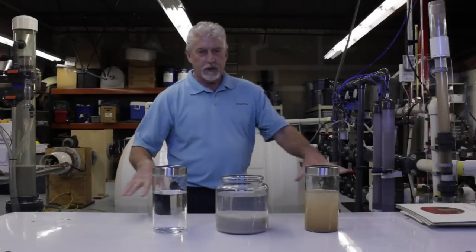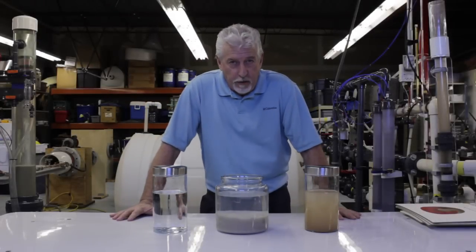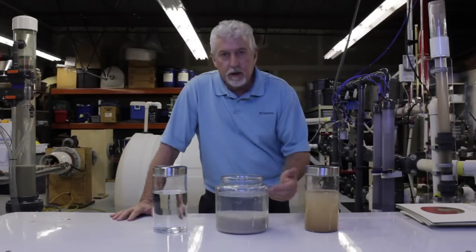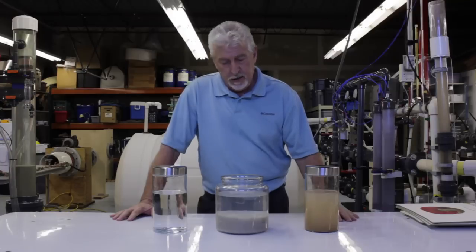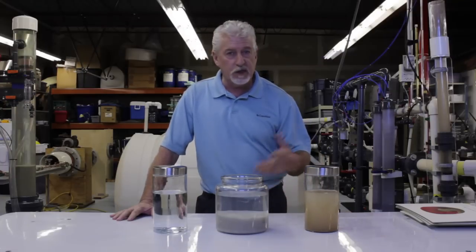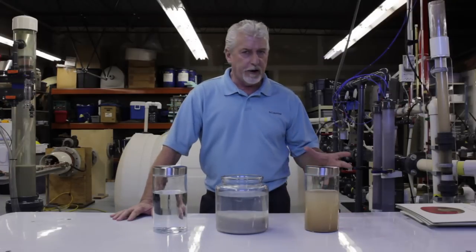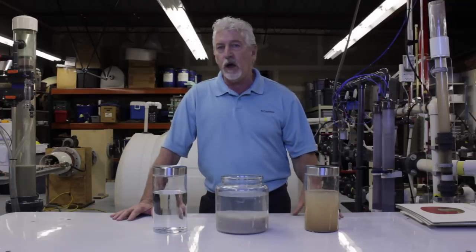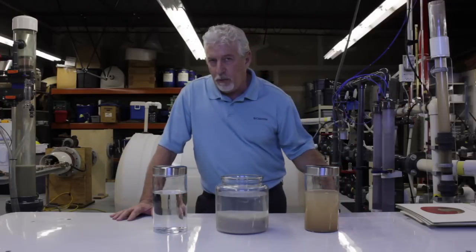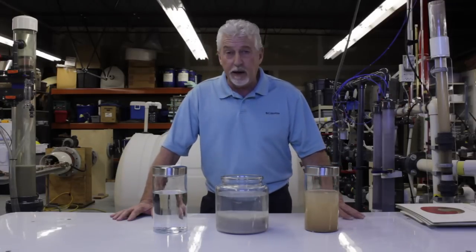So there you have it, folks. Of the three types of conventional high flow water filtration, the most popular unit is the sand filter. It's a machine. Filter, backwash, just a valve change. No filter cartridges to clean or replace. No sacrificial media to pre-coat the filter. It's simple to run, it's automatable.